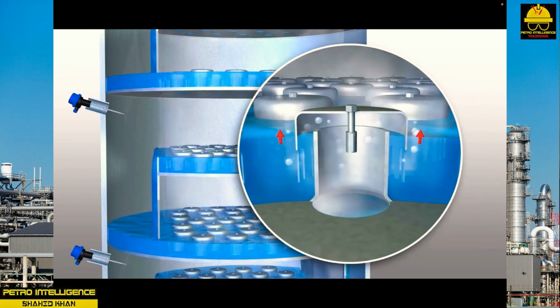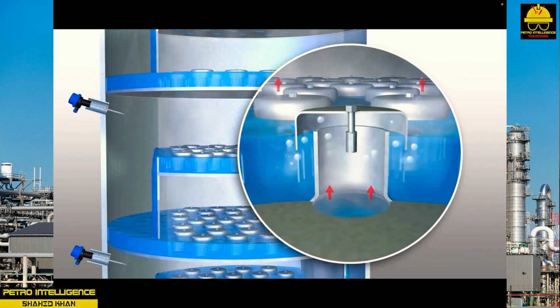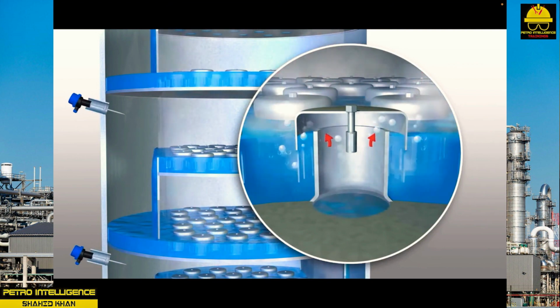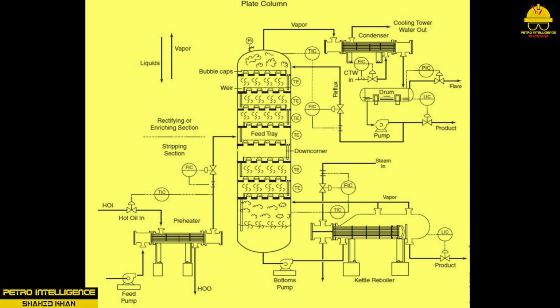During the distillation process, a mixture is heated until it vaporizes, then is recondensed on the trays or at various stages of the column where it is drawn off and collected in a variety of overhead, side stream, and bottom receivers. The condensate is referred to as the distillate. The liquid that does not vaporize in a column is called the residue.